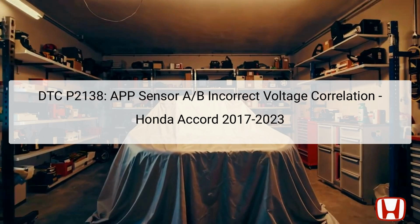When the DTC P2138 is triggered, it usually corresponds to an inconsistency detected between the signals from these sensors. The APP sensors are generally located near the accelerator pedal assembly, integrated within the pedal module. This fault can affect vehicle performance, as the PCM relies heavily on accurate throttle position information to optimize power delivery and emissions management. Consequently, proper troubleshooting is essential to either identify component failure or rectify wiring issues.